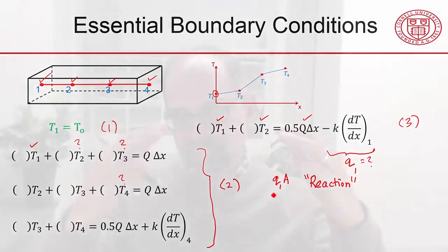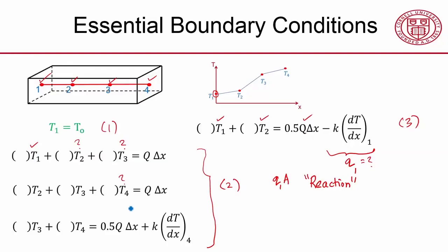And this 3-step process is very general, and any finite element solver is going to use this 3-step process. Step 1 and step 2 are necessary, and step 3 is highly recommended to check on whether your solution satisfies fundamental physical principles such as energy conservation or equilibrium.